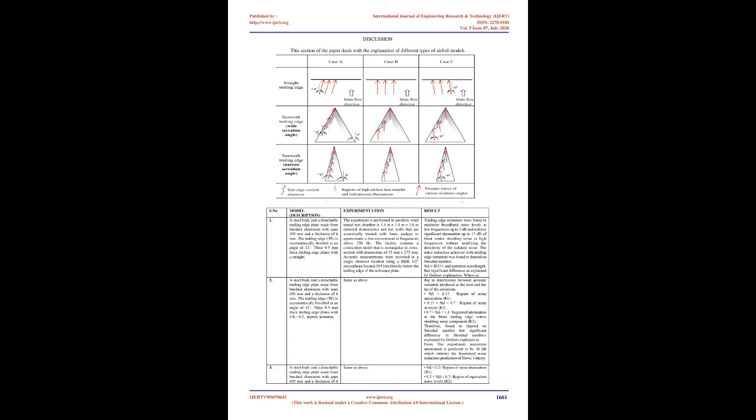Results revealed that the surface treatment can significantly reduce the surface pressure fluctuations near the trailing edge, lessen the spanwise coherence and spanwise length scale, and reduce the convection velocity of the turbulent structures. It has also been shown that the cross-correlation between the turbulent structures within the outer region of the boundary layer and the unsteady surface pressure can be significantly reduced.